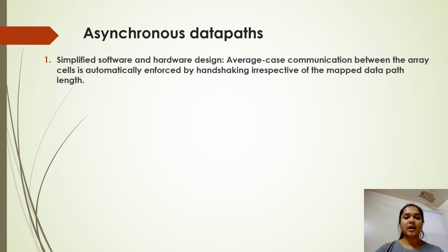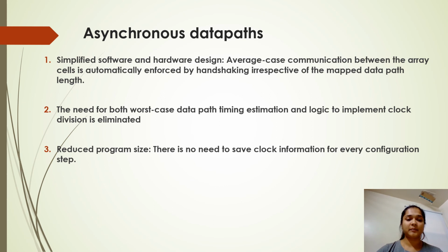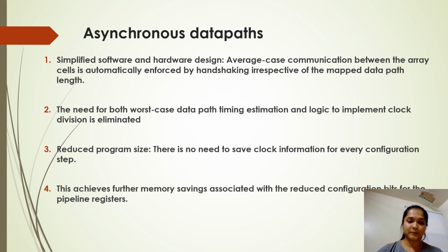Simple software and hardware design. Average case communication between the array cells is automatically enforced by handshaking irrespective of mapped data path length. The need for both worst case data path timing estimates and the logic to implement clock division are eliminated. Reduced program size. There is no need to save clock information for every configuration step. This achieves further memory saving associated with reduced configuration bits for the pipeline.